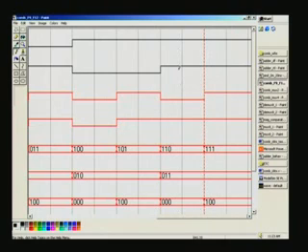For example, 1 1, and so it produces this, right? So it is 1 1 0. So it continues to be 1, and here it is 1 1 1. So two or more 1s will produce a 1 output. Thus we have verified the functionality of this majority logic.